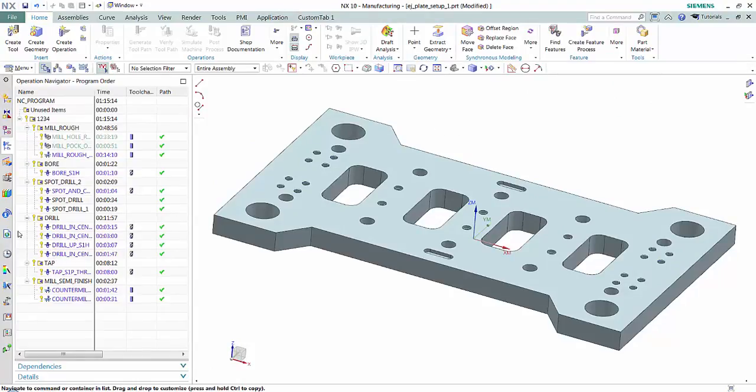Right, and I also want to make mention that we can turn off and on these tabs over here on the resource bar. So there are several of these that you may not use, so you can actually turn those off and on. One way to do that, for example here, we're going to take this HD 3D Tools and right click on it, and we can actually just hide that tab. So again, to kind of clean this up, so the ones maybe that you don't use or don't use often, you can just simply hide those tabs on the resource bar.